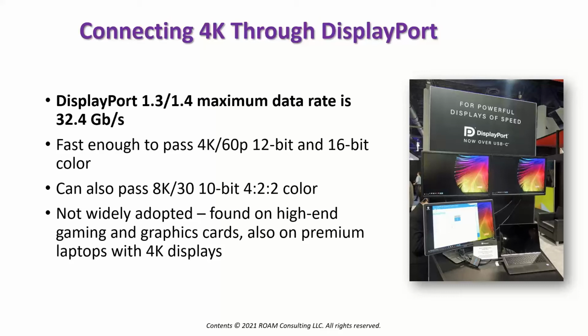So if you have both HDMI and USB Type-C on there, you can have two displays running at the same time. This is a trend that we're seeing in the industry. It's to reduce the number of connections on laptops and mobile devices to, say, one connection. And it's a so-called smart interface. It knows what you connected to it, and it configures itself accordingly. And by the way, just because you're using USB-C as a display doesn't mean you can't also do data interchange through that connection and also power for charging the mobile device. So it can do up to 3 things at the same time.